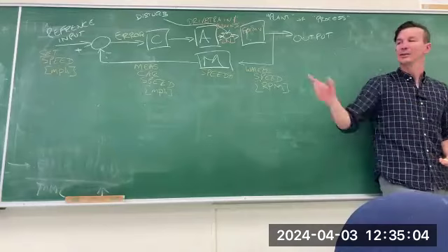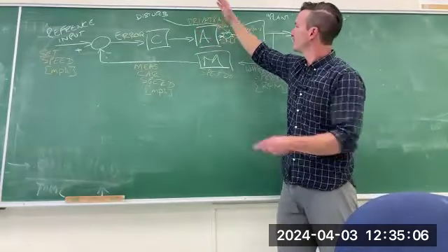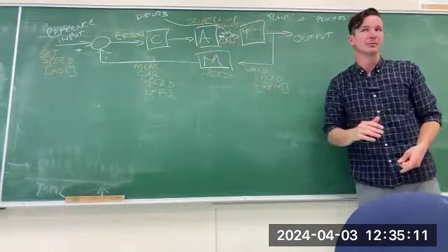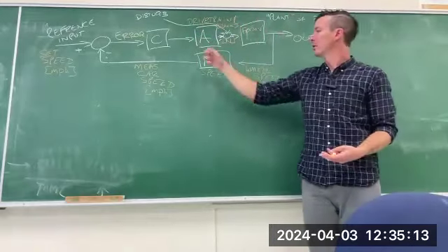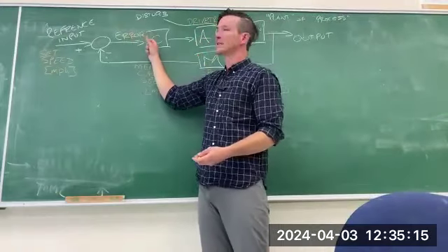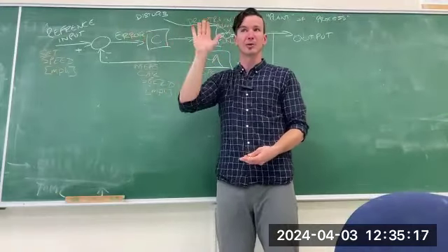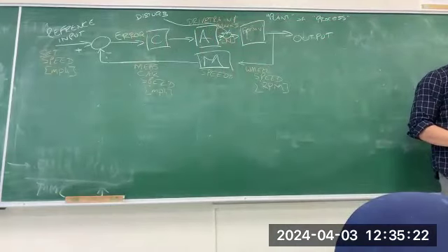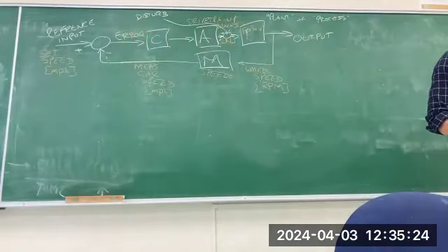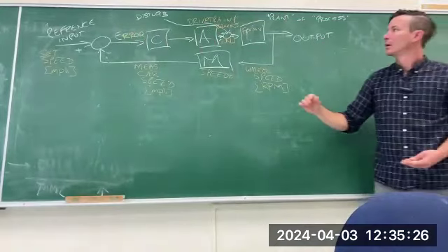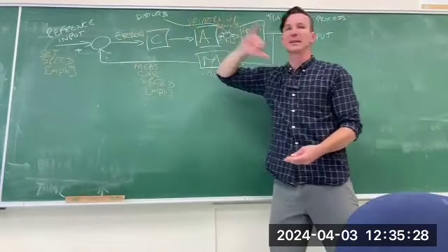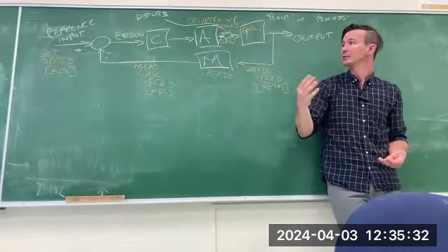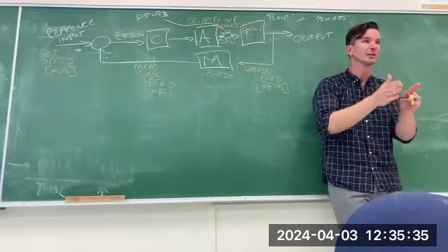You as a human are often everything to the left of my arm. When you're driving the car, you are looking at the speedometer, you are deciding what the error is, you're deciding you want more throttle or less throttle. Human in the loop is what that's called. And as mentioned, I said this was a hill. It could also be wind. It's basically whatever produces an external force on the car in the direction that you're traveling.